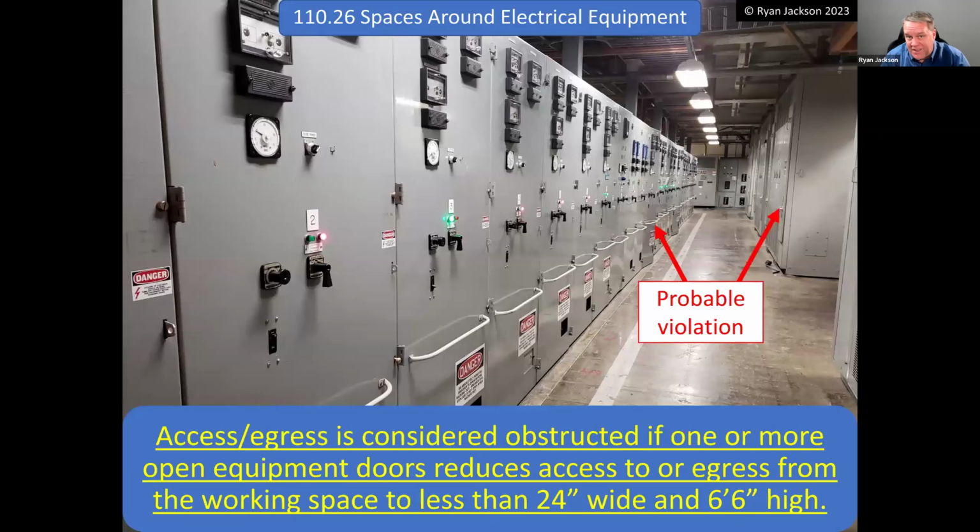Now, in an installation like this, that's a big deal. That's switchgear row 1 of 8 in that room. That room probably has to be 20 feet bigger than it did before, unless those doors have like piano hinges that open a full 180 degrees. So be mindful of this new rule in the 2023. It is a big, big deal.